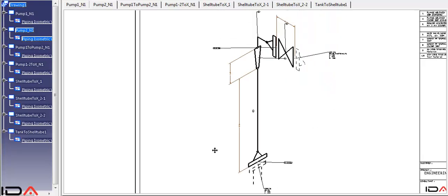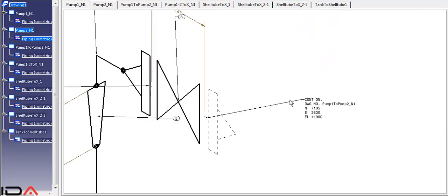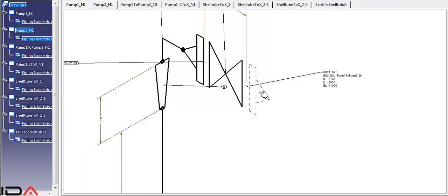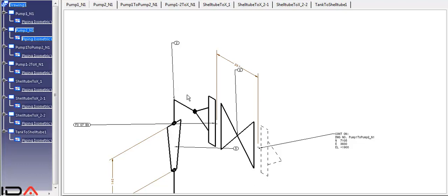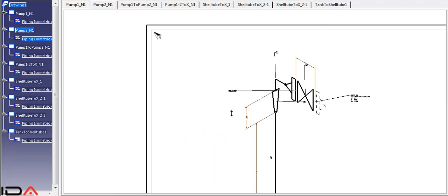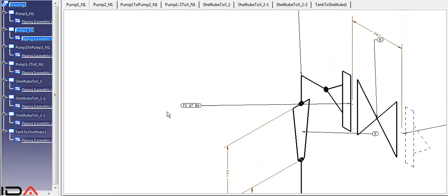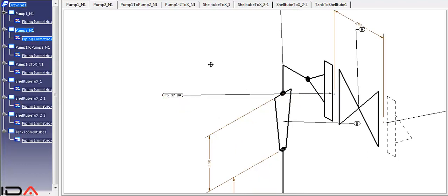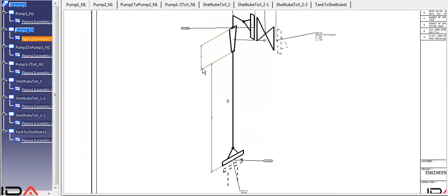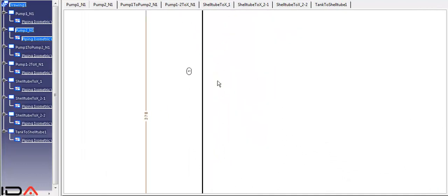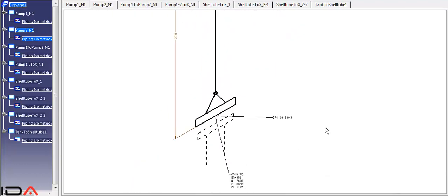And coming to the content of the drawing, it gives where it is connected to in the next spool location and what is the next spool component, the reducer component, the valve, the elbow, and also the flange, gasket, and bolt information, which is indicated in the drawing, and the dimensions which are coming automatically, the tagging of the component on the drawing.